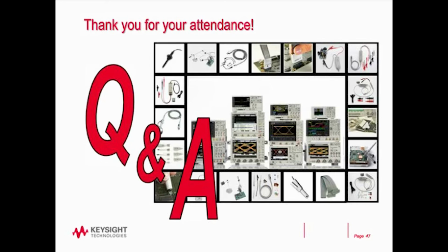Now, if you're trying to measure low milliamps and sub-milliamps, a typical clamp-on current probe is not the best solution. There are other techniques using a sense resistor, which is basically what a multimeter does to measure current. You can use your own. You can put a small resistor in the circuit, making sure that the value of the resistance does not substantially affect the operation of the circuit. It could be something like 100 milliohms, and then measure the voltage across that and convert that to current.